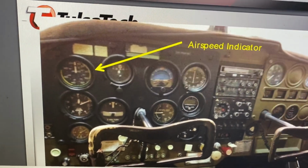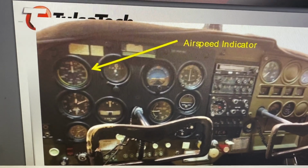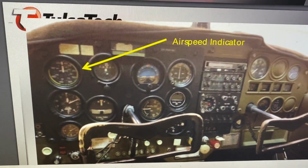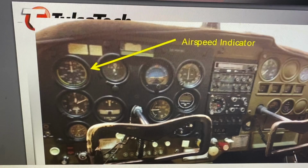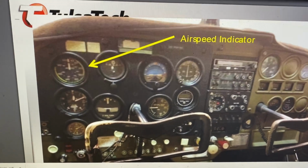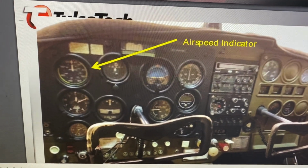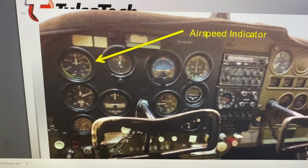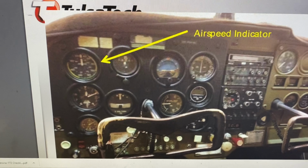But if you needed to turn the communication radios on, it doesn't mean jam out, like have a music playing radio. It means communication radios. Then you would turn them on. You would make sure your brakes have pressure. You press on your brakes. Again, I'm going through the engine start checklist. Make sure your brakes have pressure, so when you start the engine, you don't start rolling anywhere. All the circuit breakers, you'd want to make sure they're in.